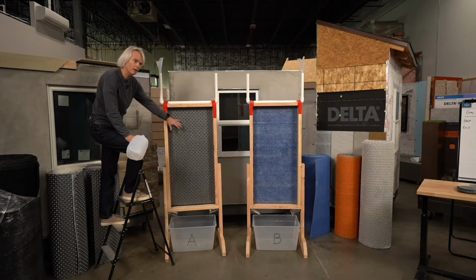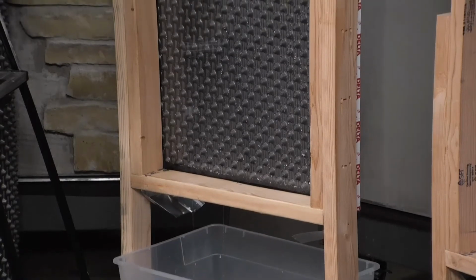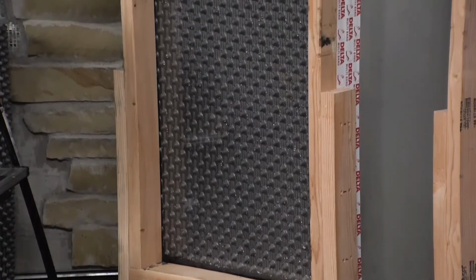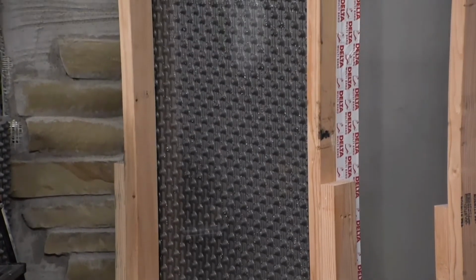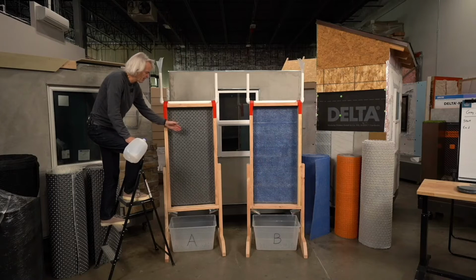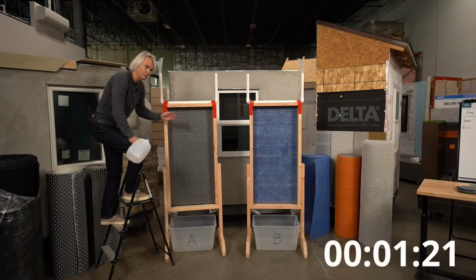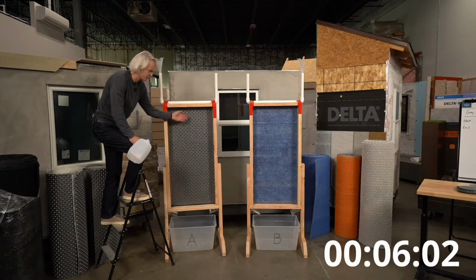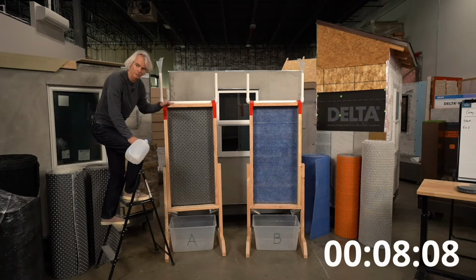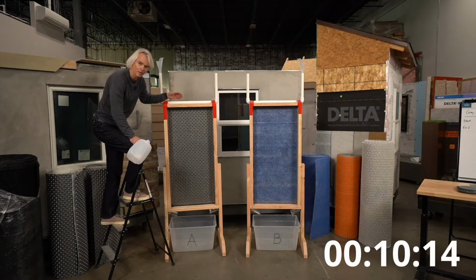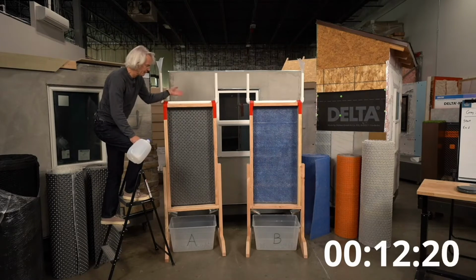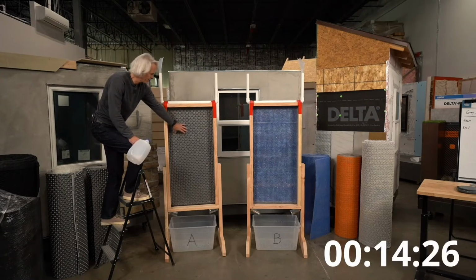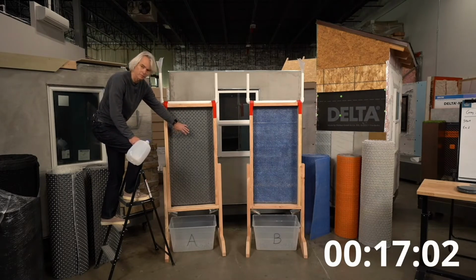And to be fair, when we talk about this one, this would be the emergency drainage system, because really we're going to show in a later clip here how fast the water actually drains on the front of this product as well, because it's an impermeable membrane, so we're draining water on the back side, but we're going to show later how fast we can evacuate water from the front side. So this one actually has kind of a dual drainage function, and this side's one of the drainage functions, but also provides ventilation of air through here as well.